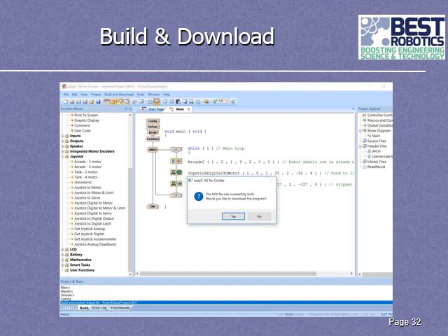When you hit the build and download, it will start running, and down in this window here, the output and task, lines will be appearing. This is the build process occurring. If there's an error in the build, it will occur here, and then of course you have to look at the specific error to try to figure out what exactly it is that went wrong.